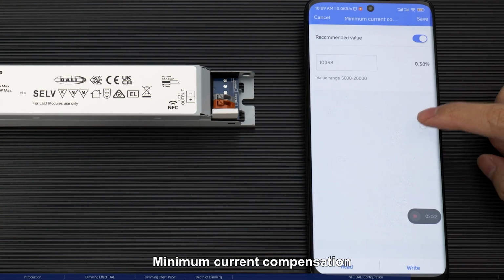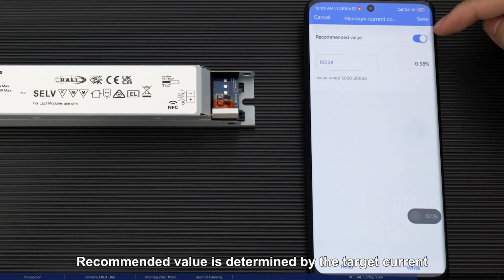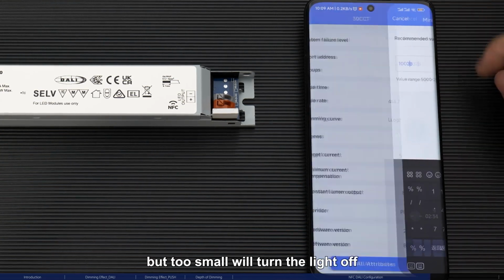Minimum current compensation. It can be used to modify the minimum brightness. The recommended value is determined by the target current. If it's not dark enough, then make it smaller. Changing it smaller will give you a lower minimum brightness, but too small will turn the light off.